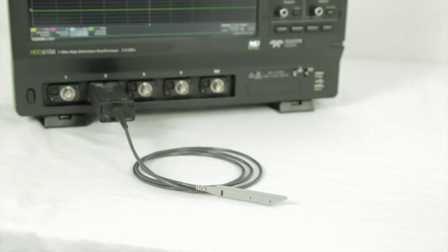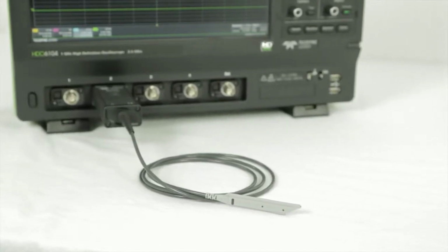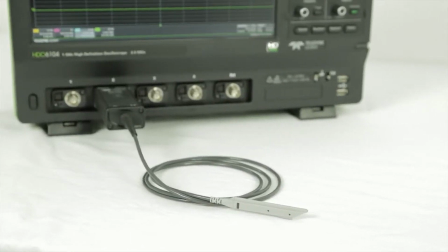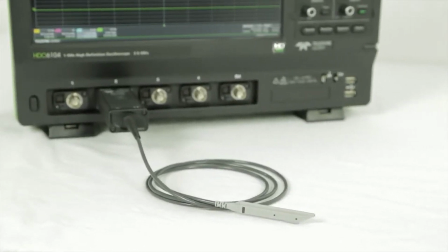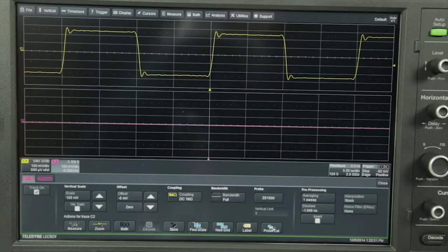The main difference between a passive probe and an active probe is that passive probes contain no active components that must be powered, while active probes contain an amplifier near the probe tip. This is most commonly based on a transistor or FET. Active probes typically offer higher overall impedance, which presents high resistance to DC voltages and low frequency signals, and low capacitance to high frequency signals. Active probes have high resistance at the probe tip, but terminate into a 50 ohm input of the oscilloscope.